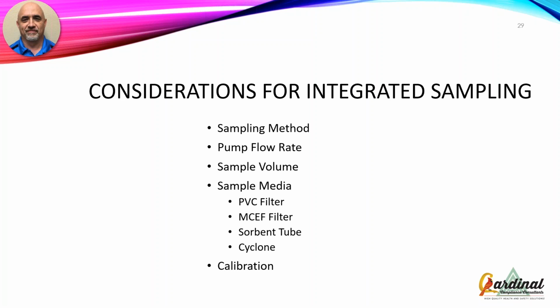And my data says less than 70 micrograms per cubic meter. Hey, we don't have anything, right? Nope. You have 70. My permissible exposure limit is 50. So if you don't draw enough air, you kind of shoot yourself in the foot by not driving that limit of detection down. That's a hard thing for people to understand.